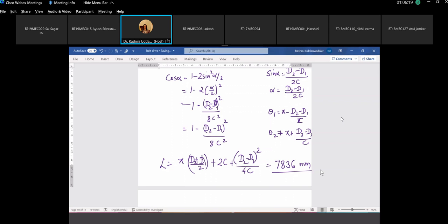In 2 minutes, let me take you to the table 15.7, pulley design. Quickly refer to this table. We have already done the gear blank design, so this part you can do on your own. You have to select the material, which we have selected as cast iron. Now the construction, whether it is an armed pulley, a web construction or a solid construction, depends upon the diameter. Our diameters are 220 and 780, which is definitely greater than 150, so we will go for armed construction, a pulley with a number of arms.